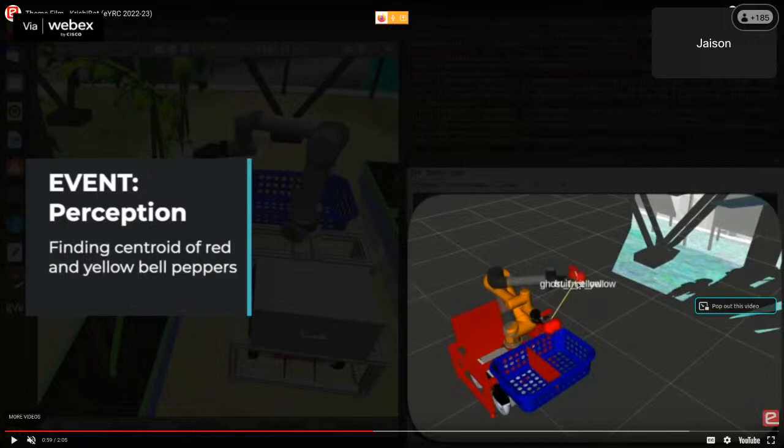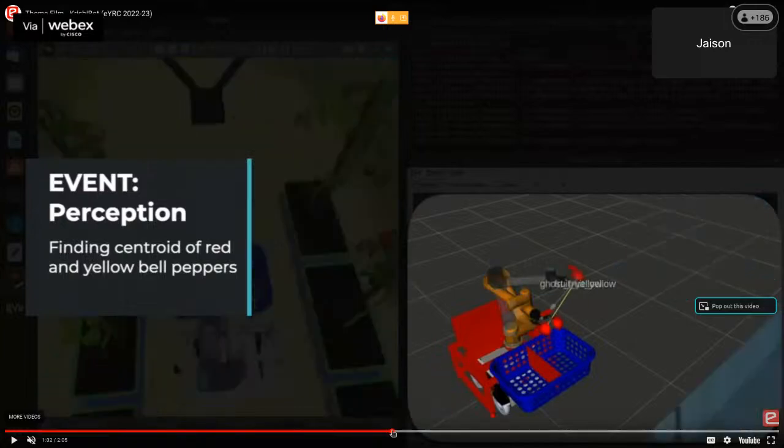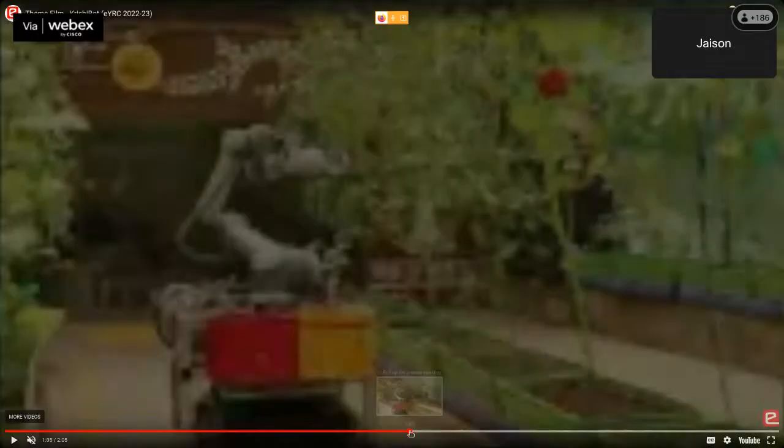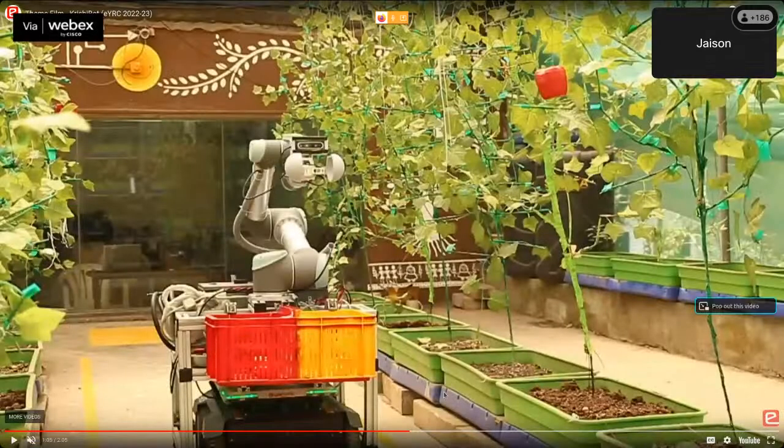Here it detected a yellow fruit, and it's showing the distance from it. It was calculated using a depth camera. In a depth camera, you get X, Y, and Z also. So that's how you localize a fruit. Here you can even know what the robotic arm is going to plan, and whether it is colliding with something else, or colliding with itself or not. All those things, for that you can use RViz. And then finally you can test it on real hardware.